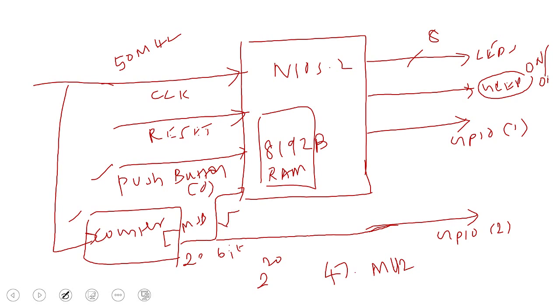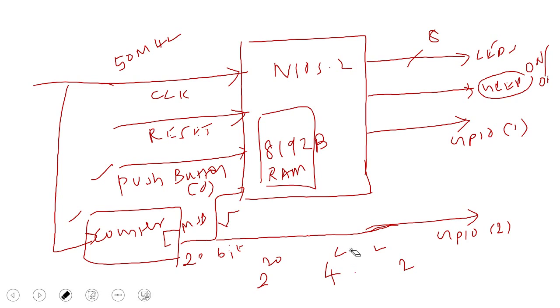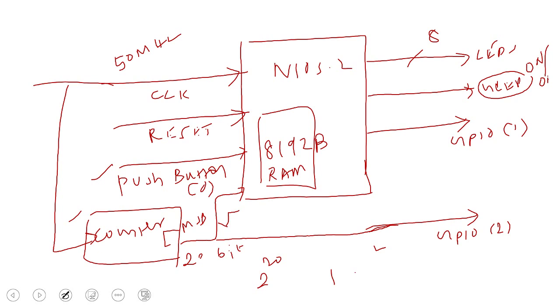So the output which is coming from this counter is in the range of 47. Sorry, slip of me, it's 47 hertz. Let me take this. The output which is coming from this most significant bit is divided 2 power 20 times by this counter, where the input is 50 megahertz. So the output is 47 hertz.